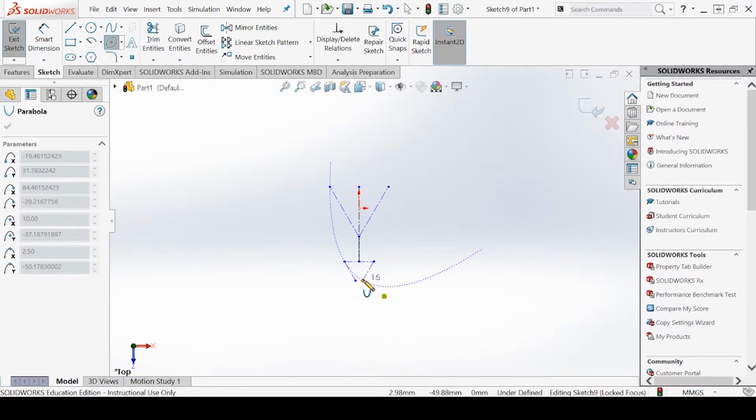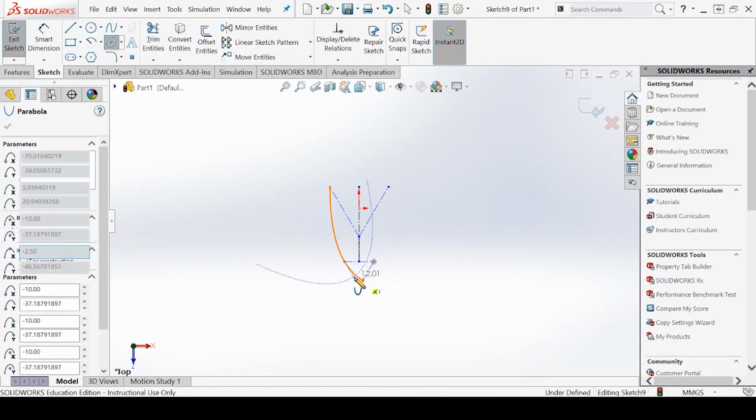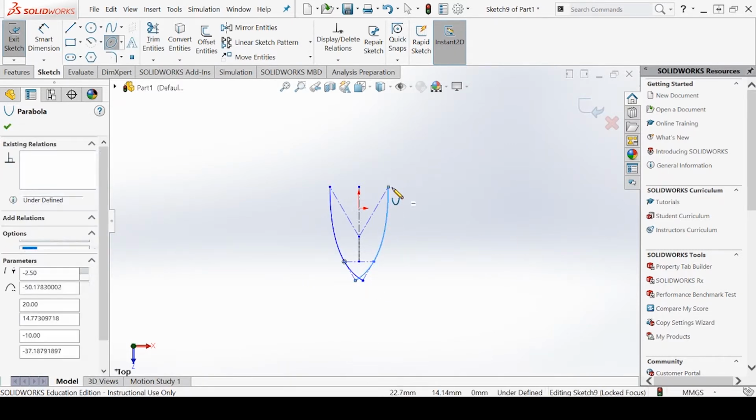If you click from this point here, and then draw back up, you'll reach a point where you hit that edge of the entrance pupil, and that's going to draw out one side of the curve of your parabolic concentrator. We're going to do the same thing on the other side. Again, drawing back up. And there you go, you have the basic shape of your compound parabolic concentrator.